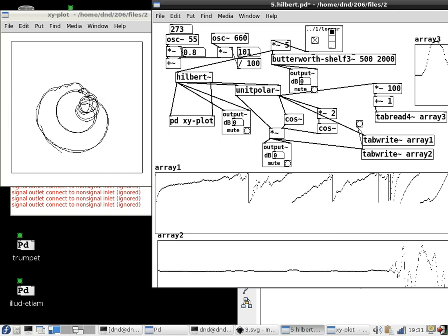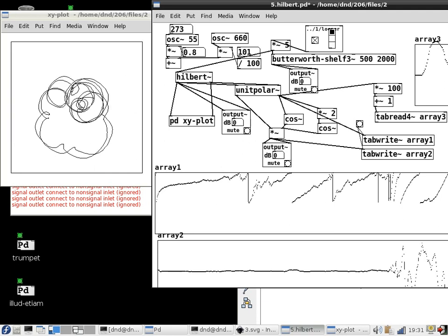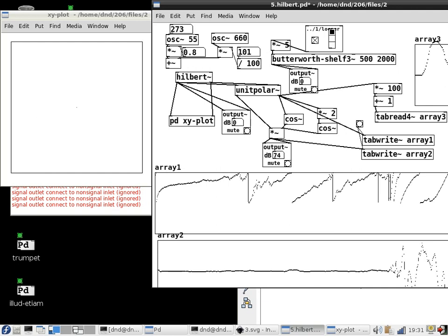So in general, when you have something that has high frequencies going in and do something that tends to double frequencies, you're going to get just raging, I don't know what, paper sound coming out, right? So really what you want to do, in practice, is reach for this nice Butterworth filter that makes things behave better. And now we have kind of a reasonable collection of timbres. Oh yeah, that's the original. Okay. And now that's a pretty controllable thing.